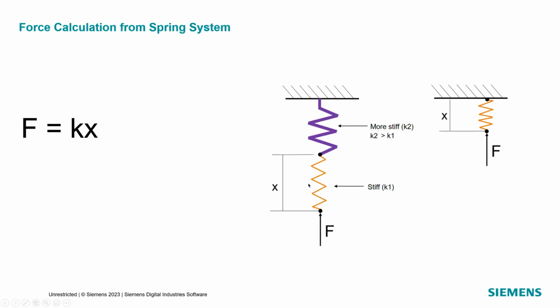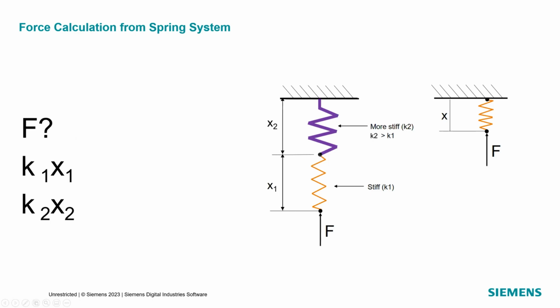When we go to determine the force, we're typically looking across the displacement X1 only, but there's some displacement or give in the supporting structure. If there's a lot of give in it, it can mess up your force estimate.